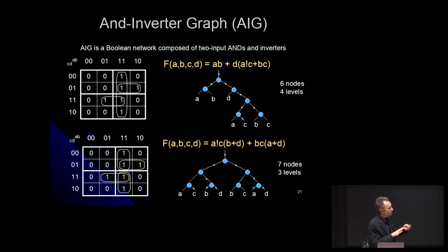So ABC would derive multiple structural representations and put them together into this AIG with structural choices. And then when the technology mapper comes along and tries to map, it will use either delay optimal or area optimal, depending on whether this piece of logic happened to be on a critical path or off a critical path. So this is all done automatically, and we appreciate the generality of this.